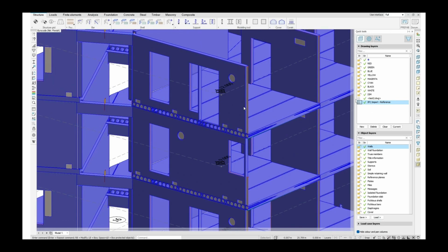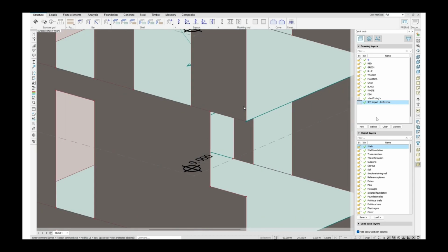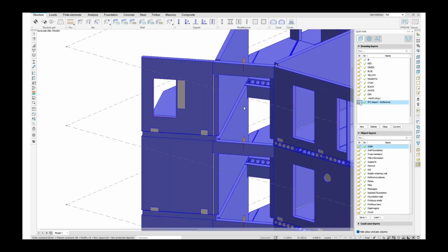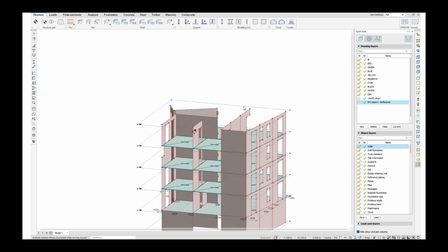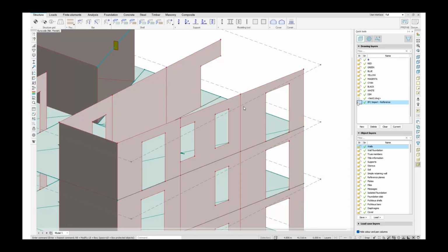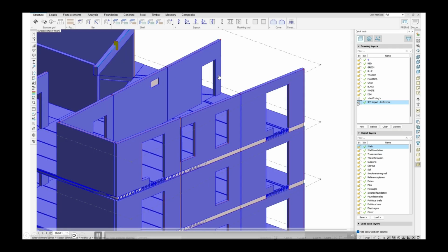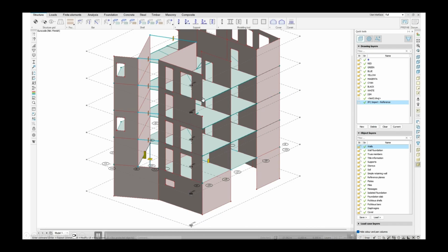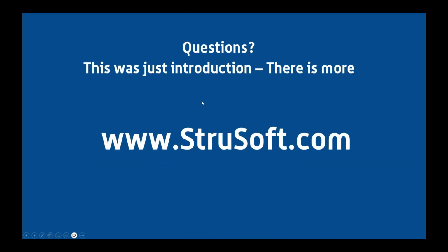So we can compare the analytical model and the original geometry together, so we can see how much simplification we have done when we did the conversions. For instance, this wall, we removed a lot of stuff. So it's a really quick way to check that you have every possible column in your system and you haven't done anything stupid when you fixed your model. For instance, if you look at this one here, it's probably not reasonable to remove that part of the element, but you can see it with the 3D model really easily if you just save the original geometry.